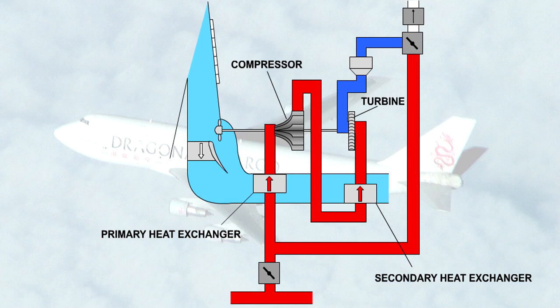The air is now used to drive the turbine, which in turn drives the compressor. The pressure drop across the turbine produces a large temperature drop. The pack cooling fan is used to supply the heat exchangers with cooling air on the ground and during low-speed operation.